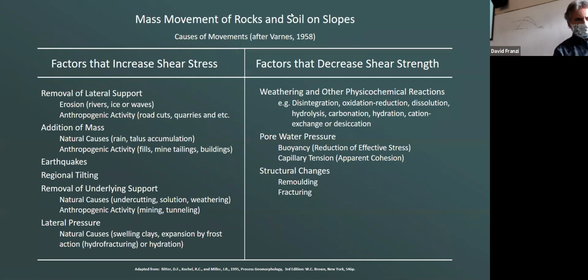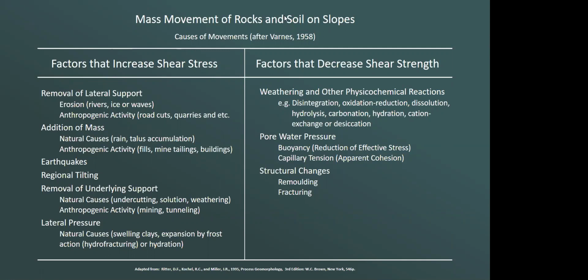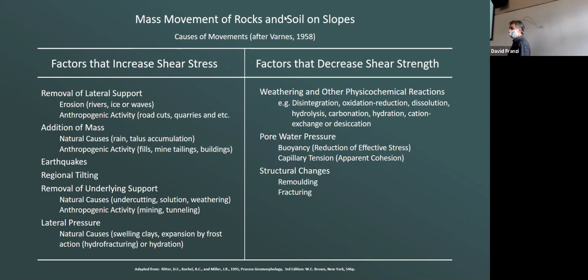Any questions? You guys in the online group, you're all set? Yes, sir. So when you go back to the Bishop method, then you look more like viscous sediments that you maybe see that? No, all you're trying to do is account for all of the forces that are operating on the slices. Fellenius is just a quick method to get a good approximate answer. And it's very adaptable. There's a lot more calculations. I mean, now in the day of high-speed computers, it doesn't really matter. You could do Bishop method and account for those side forces. Fellenius just ignores the side forces. Okay. That's the big difference between them.